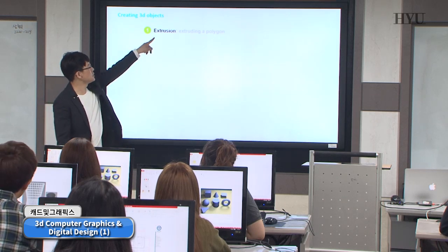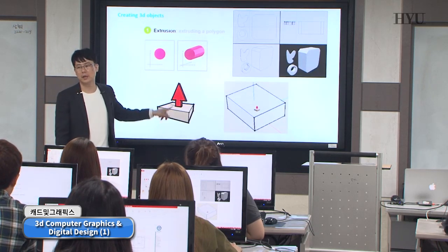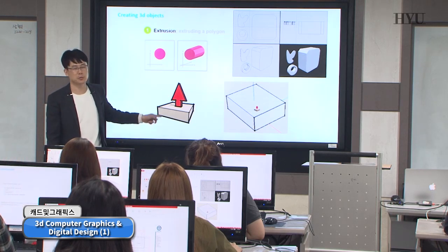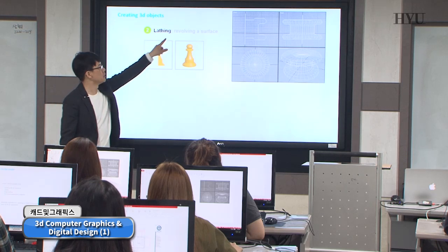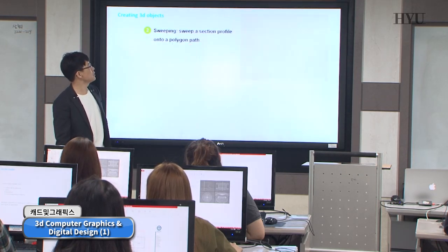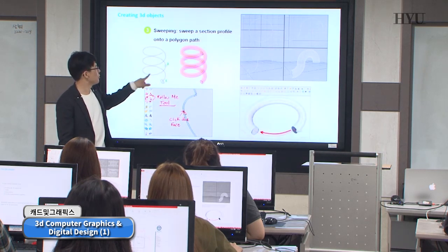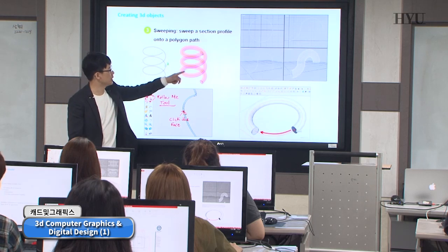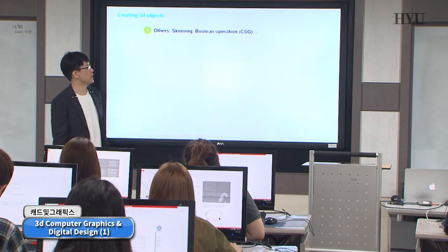The first way is extrusion: drawing a section profile and extruding, push-pull. Next one is revolving, revolving a section profile. That's the second way. Third way is sweeping: section profile, pathway, and 3D. The Follow Me tool is similar to the push-pull tool. We reviewed this one last week.